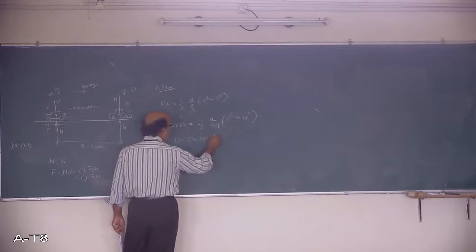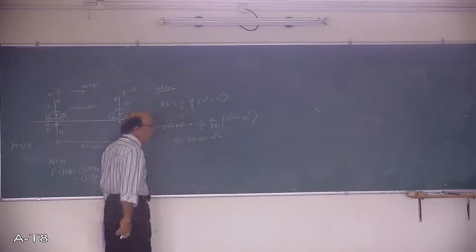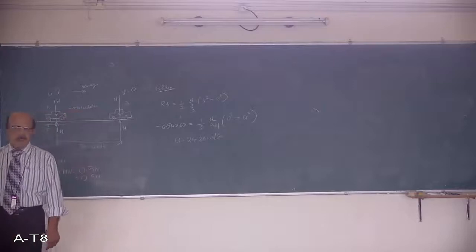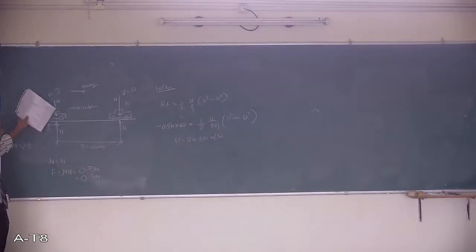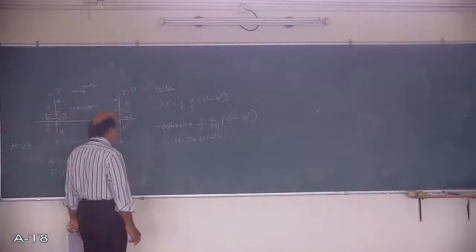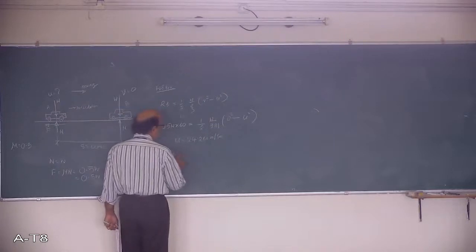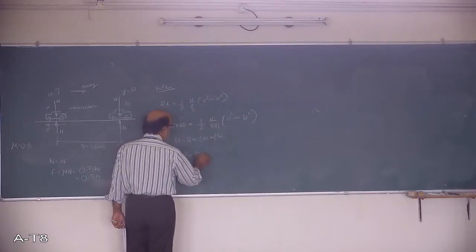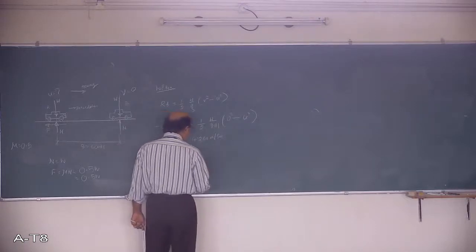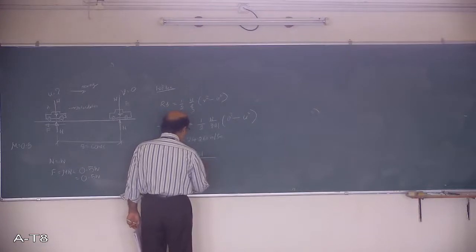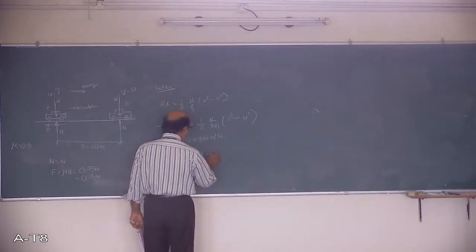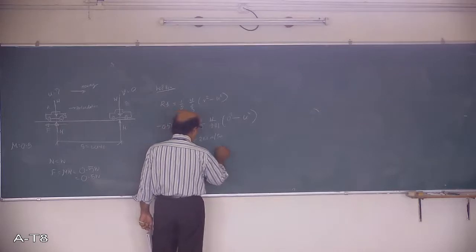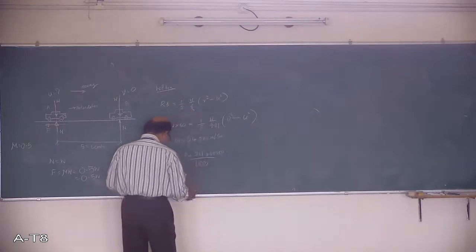24.261 meters per second is the initial speed of the vehicle. That is, before applying the brake, its velocity will be 24.261 meters per second. Now you can convert this into kilometers per hour. So for that you multiply 24.261 meters by 3600 divided by 1000, converting to meters per hour and then kilometers.